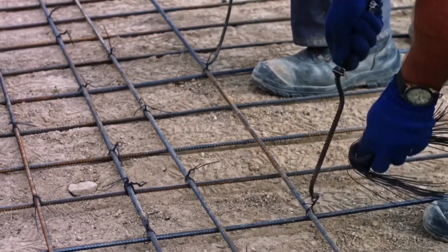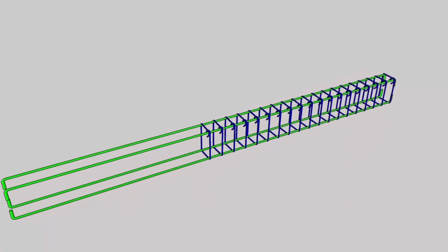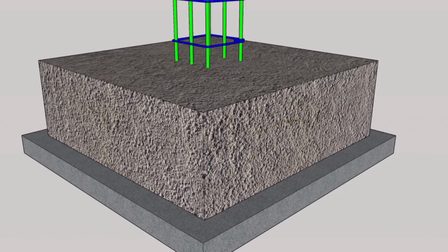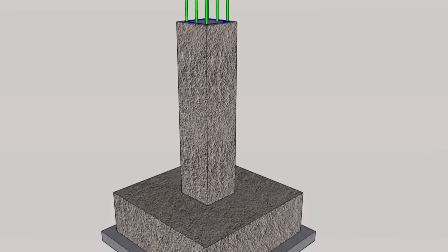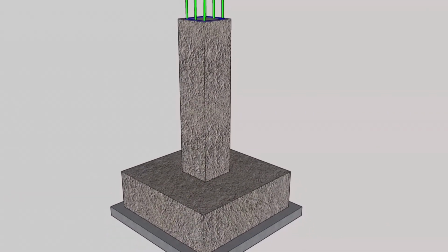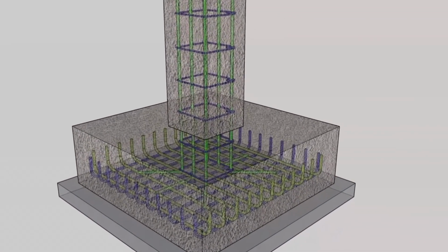Steel is the most widely used material for reinforcing concrete elements. The two materials bind together without any slippage and thus act together as a single unit in resisting the applied loads and adding to the tensile strength of the concrete.